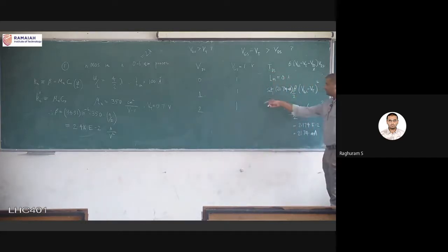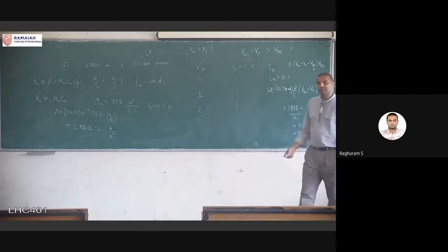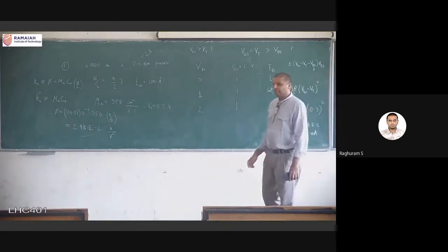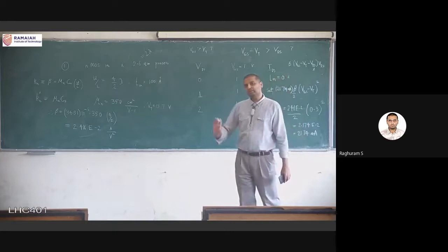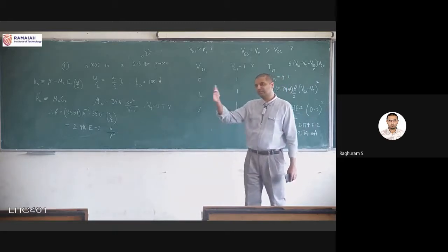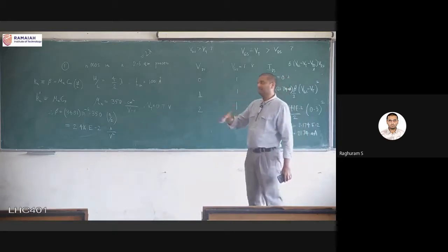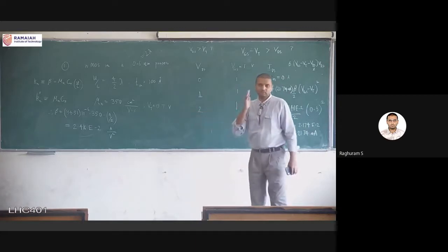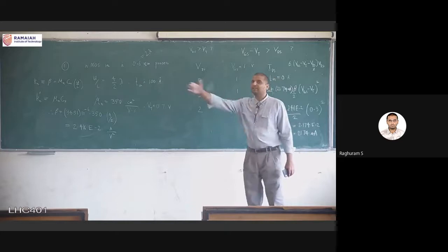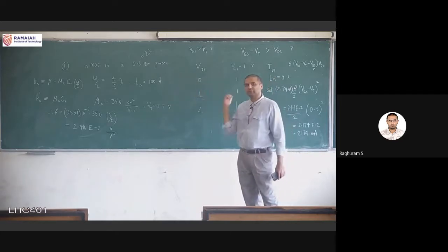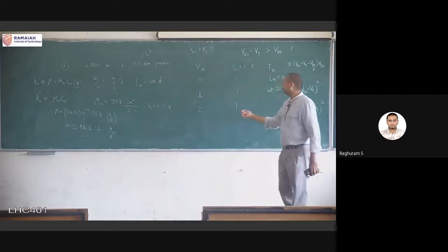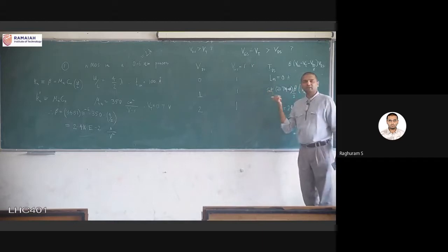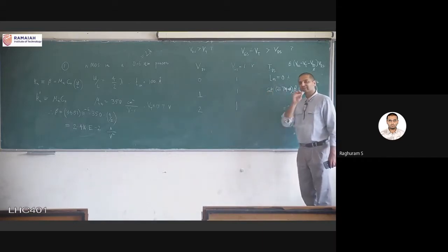And the next case, it's very easy for me because the transistor continues to be in saturation. VDS has increased. Okay, as VDS is increasing, it can never go from saturation back to linear. The one side is linear, everything else is saturation. So for the third case, I don't have to calculate this again. I know it is saturation. Our equation says that the current is going to be the same. It is the same value.